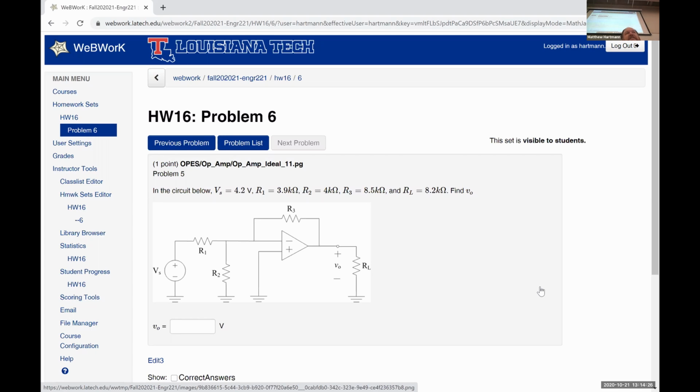So then it's just a very simple circuit with those two resistors to where you would apply Kirchhoff's current law at this node and find that the current flowing through the resistor R1 is the same as the current flowing through the resistor R3, and then solve for V out, which is what we did a couple of different times. All this stuff is fairly trivial. Like, you know, the in-class assignment problems are probably significantly harder than what I would put on the test with regards to op-amp circuits.